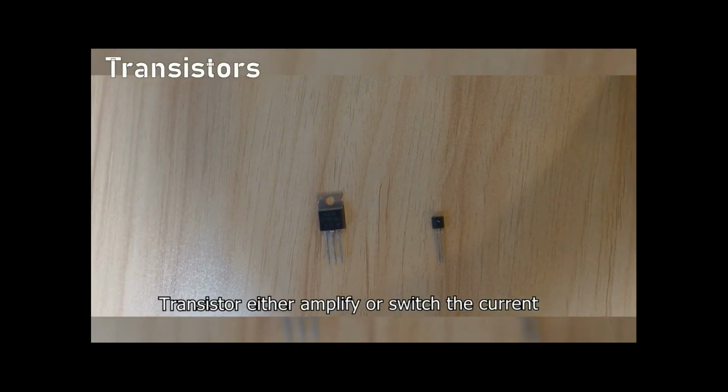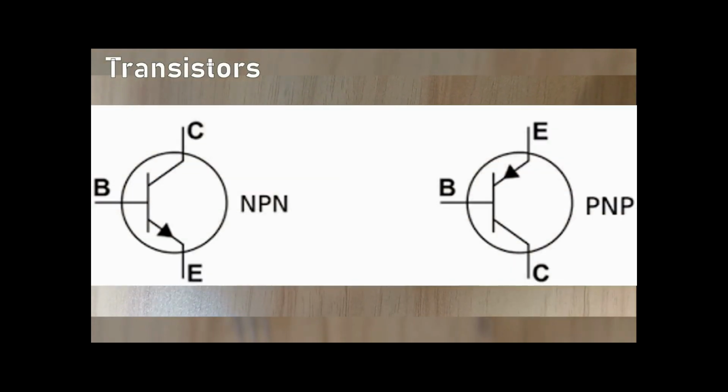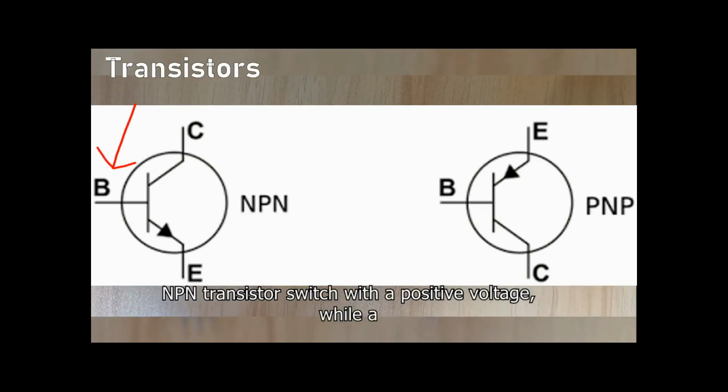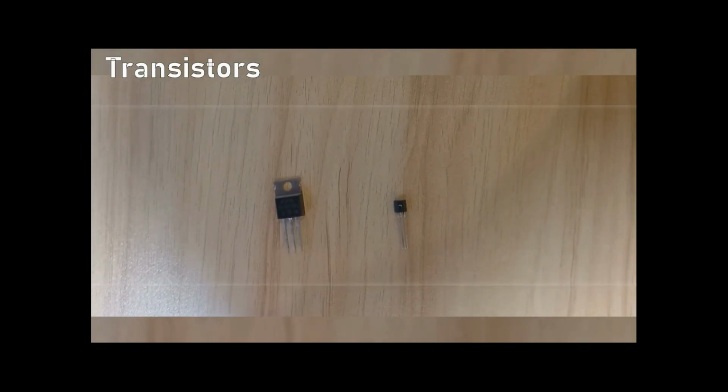Transistors either amplify or switch the current. They are controlled by the current on the base pin, which is this pin. NPN transistors switch with a positive voltage, while PNP transistors switch with a negative voltage.